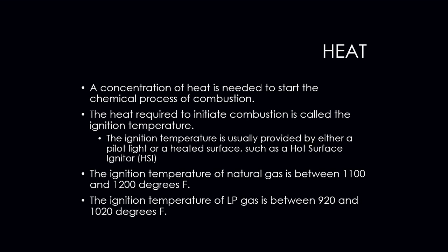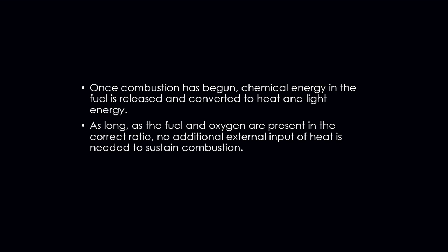The ignition temperature for LP is anywhere between 920 and 1020 degrees. The reason we have a difference in temperature is because of the difference in chemical composition between natural gas and LP. Remember, natural gas has a specific gravity that is lighter than liquefied petroleum, or LP. Once combustion has occurred, the chemical energy in the fuel is released and converted to heat and light. And as long as that fuel and oxygen are present in the correct ratio, remember, all three of those have to be in the correct proportion, no additional external input of heat is needed to sustain combustion.